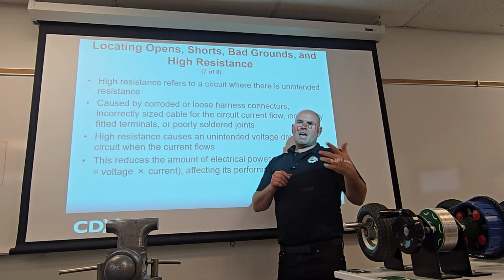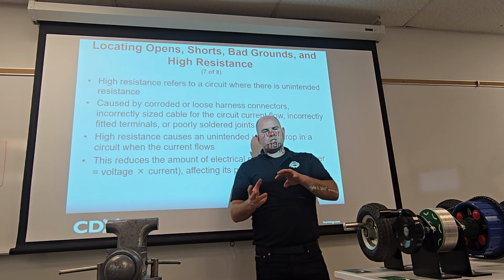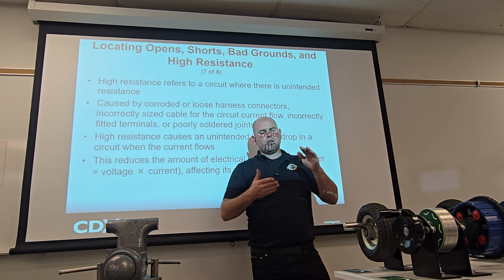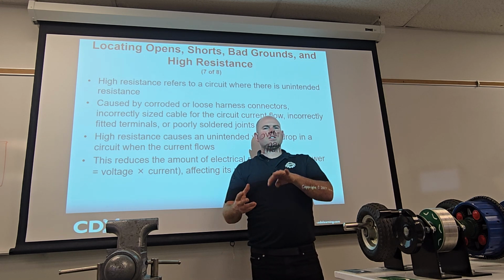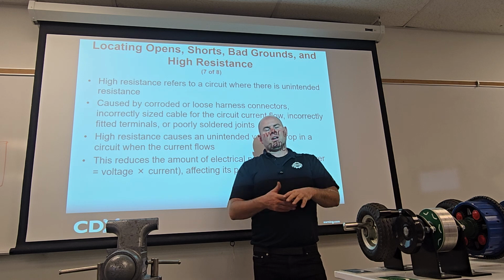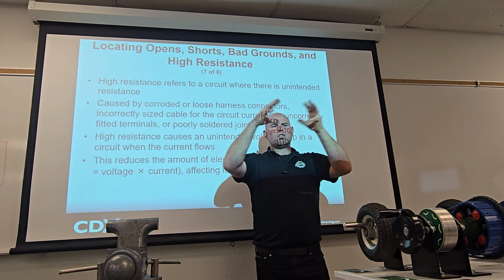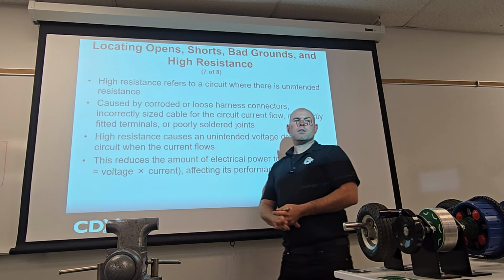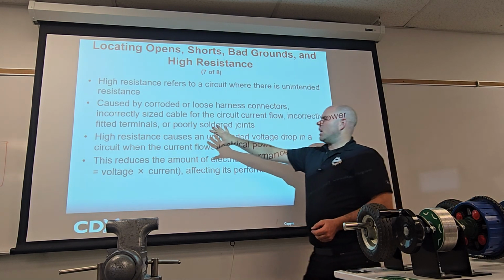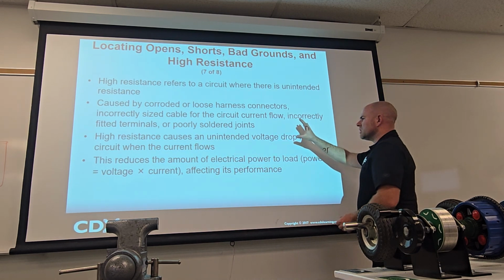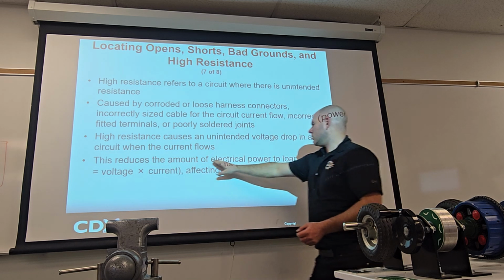If yours does that, it might be simply due to unwanted resistance somewhere, maybe in the switch, maybe in the wire, maybe in the connector, or sadly, there could be a problem with the motor too. But the way we test if it's the motor or the circuit is test the motor for the voltage drop. If your motor is dropping 12 volts and it's still slow, it's not the circuit. But if your motor is only dropping 8 volts, that means something else is consuming 4, it's in the circuit. Make sense?